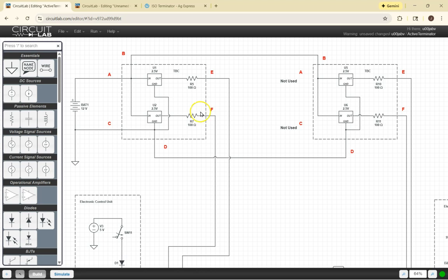Granted, yes, it does help maintain that 2.5 volts during the recessive state, but each controller is responsible for putting that 2.5 volt bias on as well. These devices just help regulate that better. As I said, they do a better job, but I guess it's been determined that we don't really need anything that does that good of a job, because these have been eliminated over the years and replaced with 120 ohm terminating resistors.